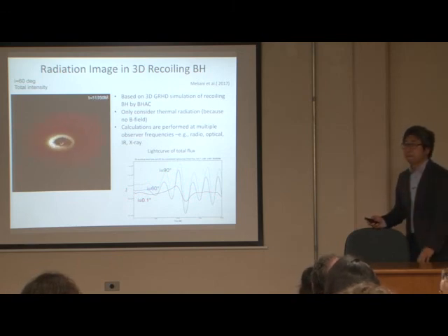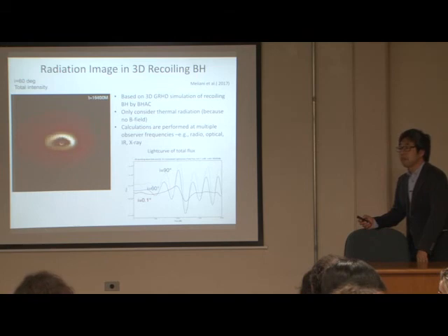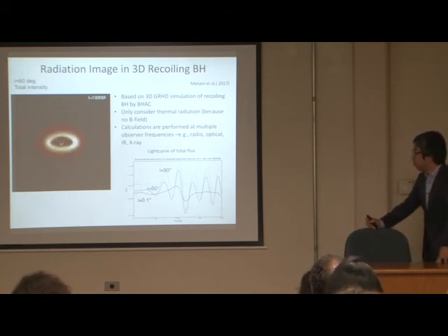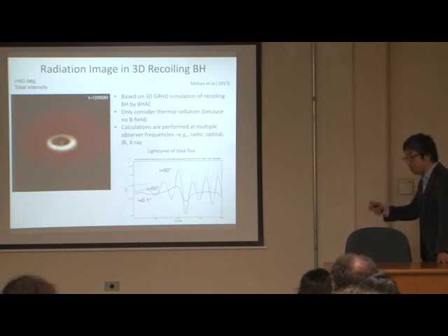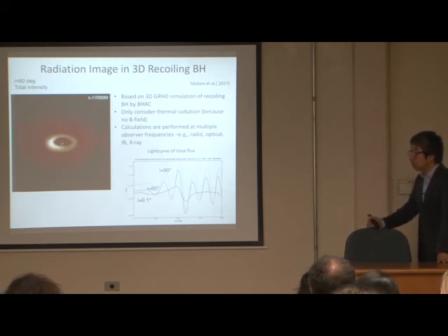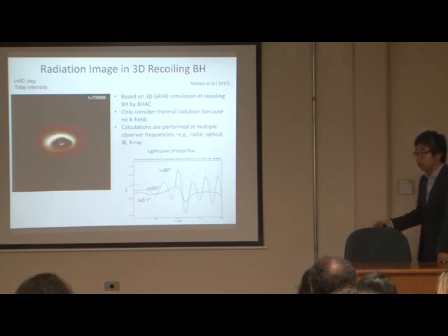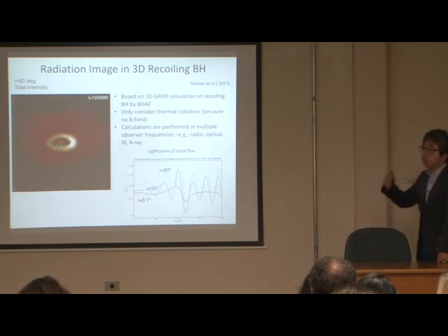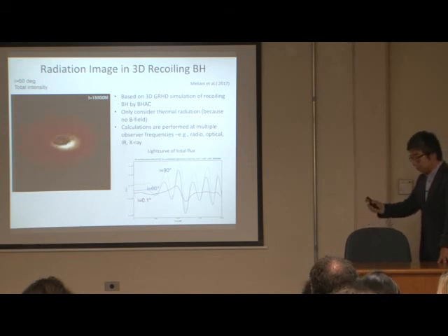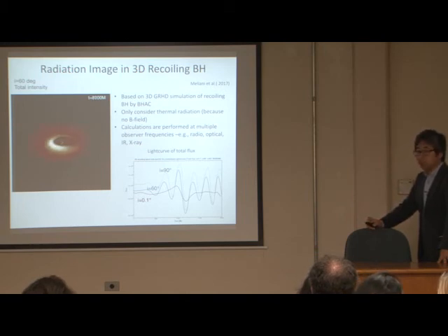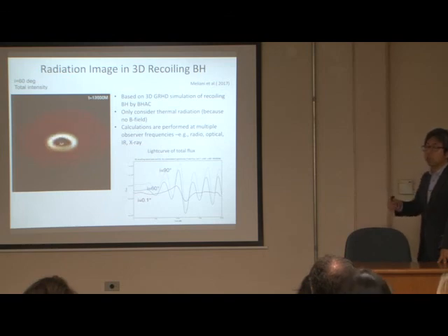Just for curiosity, in the case of adaptive mesh refinement, what is the condition to refine? Yes, this is a big point. In this case, we are doing it two ways. One is a Löhner scheme we can consider. This is the second derivative of some quantity, like density, pressure, or velocity. If it goes above some threshold, we can make it reconstruct, making an additional level. Or in this case, we also try a shock-capturing scheme to look for where the shock happens. Then following this shock structure, we can adaptively make higher refinement.